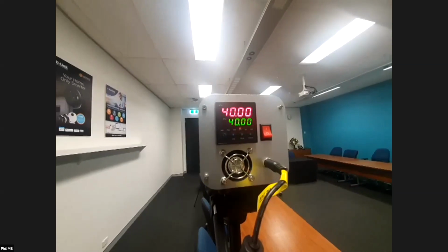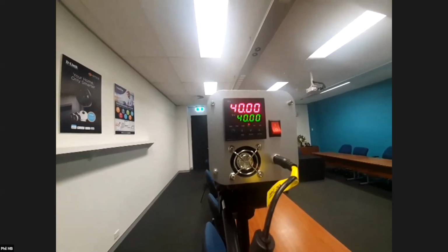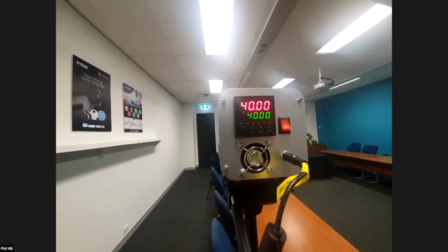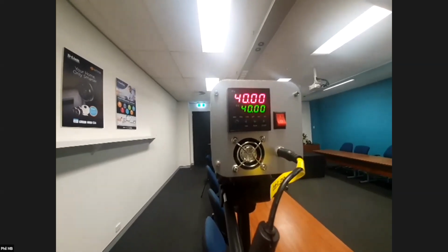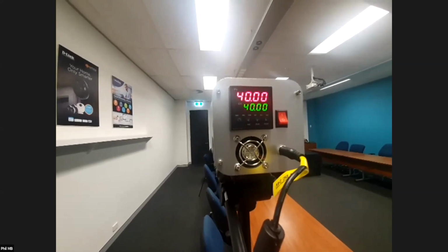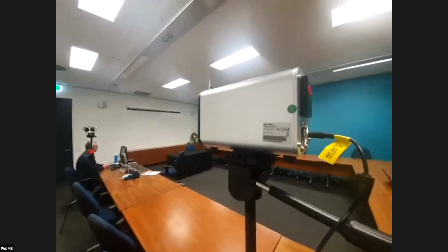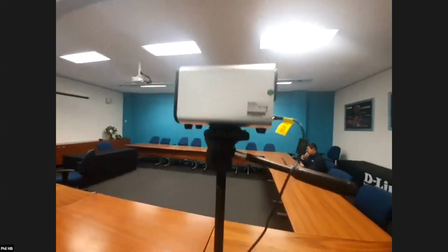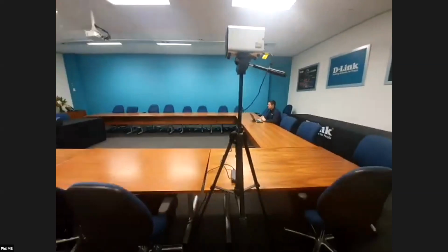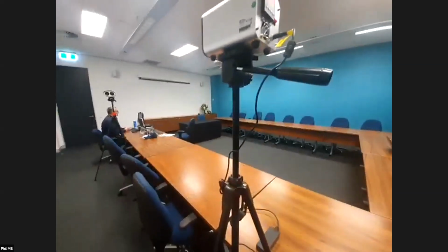So when you're setting it up, you need to set the temperature. Out of the box, it comes preset to 40 degrees, and that's how the camera or the thermal sensor is configured to use 40 degrees as a reference point. As for the mounting itself, we've got a temporary installation here on tripods, but they can obviously be mounted permanently with wall brackets.